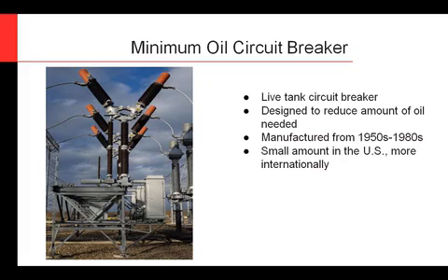So on the live tank side, we have the minimum oil circuit breaker. These were designed to reduce the amount of oil that was needed, so you didn't have this huge bulk oil circuit breaker. Once again, these have been around a while, 1950s and 1980s, but as SF6 came in and took over, these were replaced with SF6 style circuit breakers. So same thing, you can still get parts, still maintain them, but once again, they require maintenance, and so they've opted to start removing these from service and putting in SF6 style.